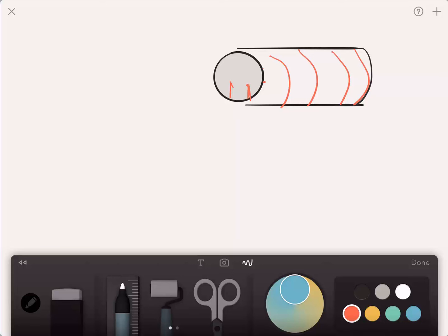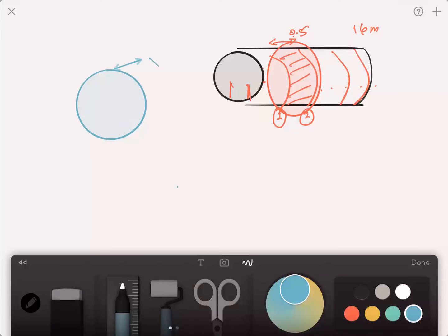What I realized is that every section which lies between the stiffeners, so if I had frames, frame 1 and 2, these are basically repeating units throughout. And it was a 16-meter long fuselage. So if I'm considering 16 meters long and this is only half a meter, then if I can just model this section, how much better would it be in terms of computational accuracy and speed? So what I did is I took out first a section which was just half a meter length. This was a frame and this was another frame. Throughout, of course, it was all round.